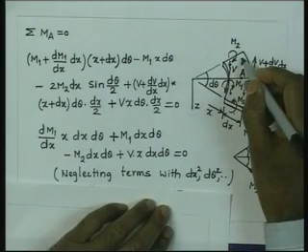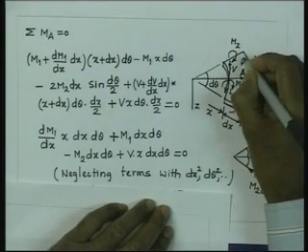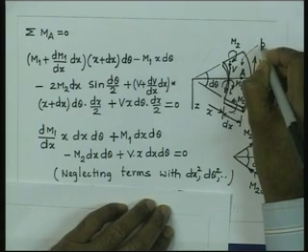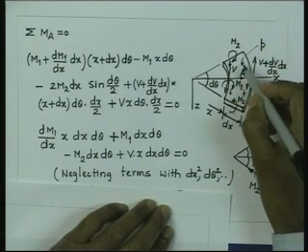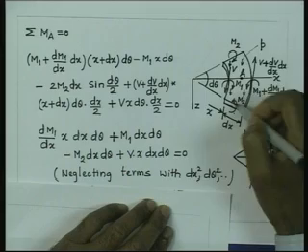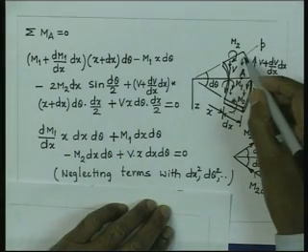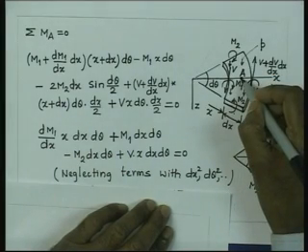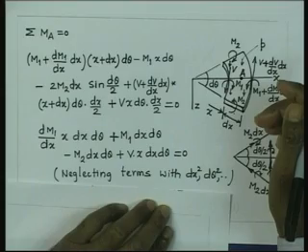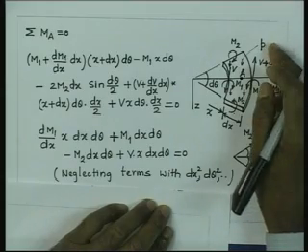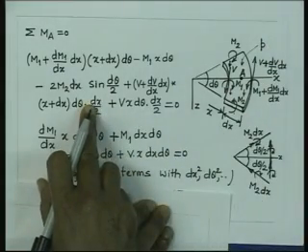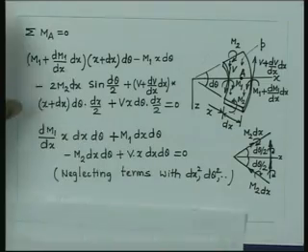We have also had the pressure. If this is the pressure P, now that pressure will be distributed all over the plate and its centroid will pass through the point A, therefore, there will not be any contribution of the pressure distribution towards the moment, that is why we have not incorporated it in this expression.